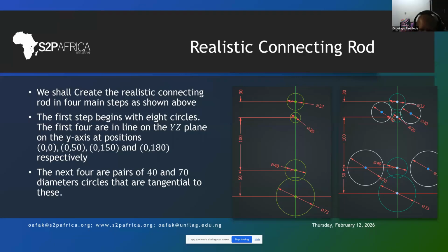So I am just going to show you how to draw this thing so that in about 2 minutes after you've started, everything you have on your drawing will be green if you just follow simple instruction. To do it, just take a plane. Here I use the ZX plane or XZ plane, and I just move to the center and create a center circle of diameter 73. If I do that, this turns green immediately.